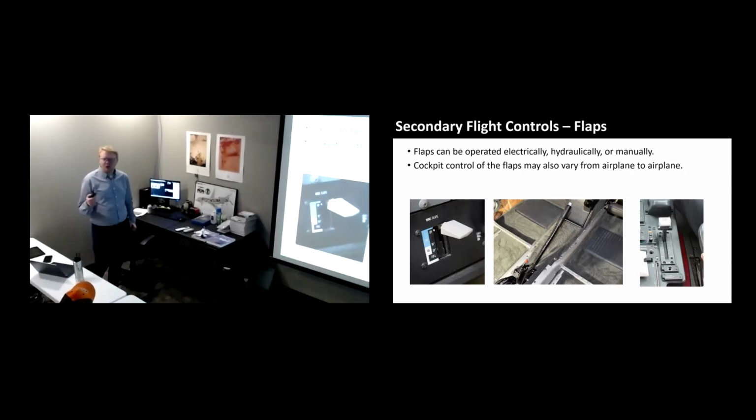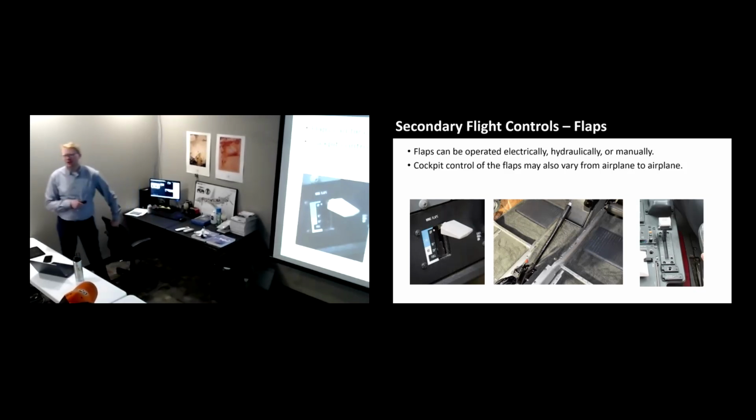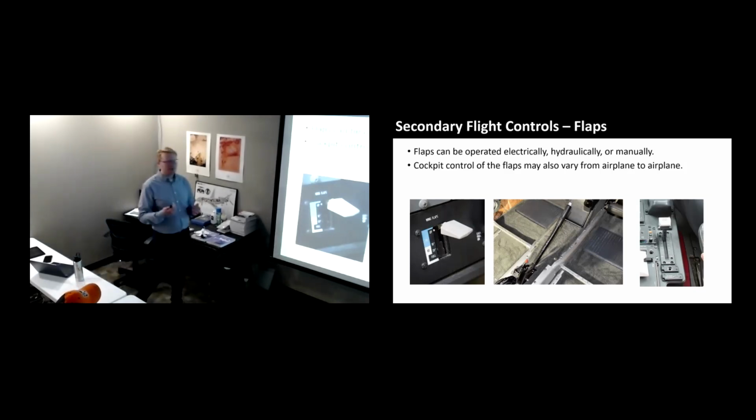They found that it produced so much drag that pilots who attempted to go around at that flap setting usually lost control of the airplane due to how much drag they caused. So Cessna said, we're just going to limit it at 30 degrees. There are very few airplanes flying around with 40-degree flaps available still, but they're out there. There are guys who want them, so if you modify your airplane, you certainly can. But usually it's about a 30-degree angle.